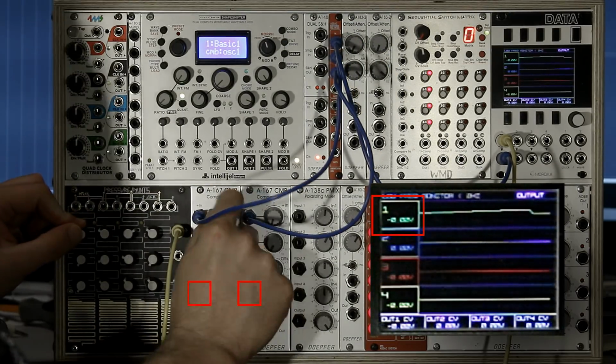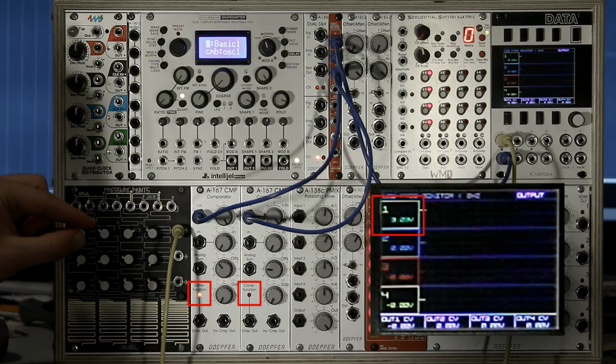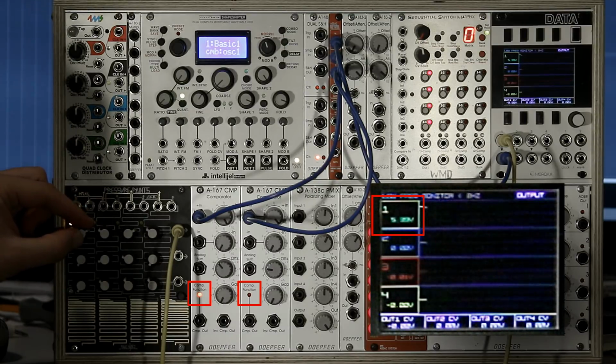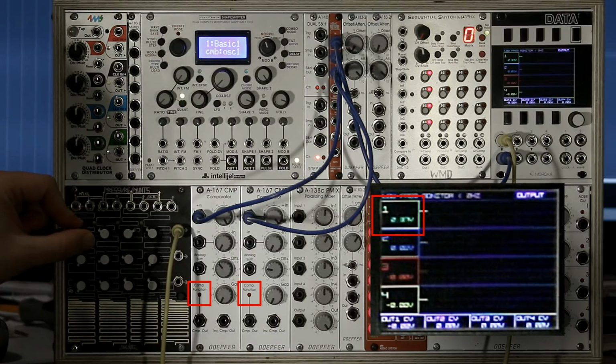Increasing the main voltage should change the state of the comparators. When it increases above 2.8 volts, comparator 1 changes its state to high. When it passes 5.6 volts, the output of the second comparator also switches to high. That is all the information we need to select between ranges of the input signal.